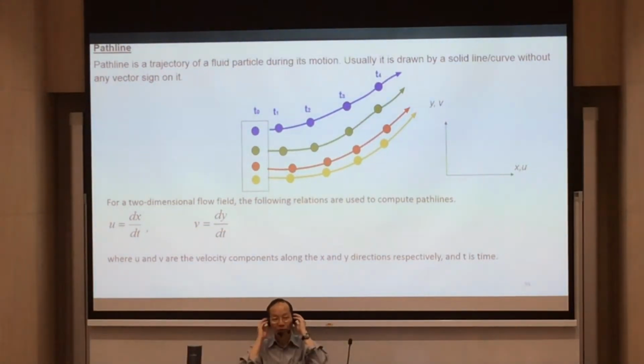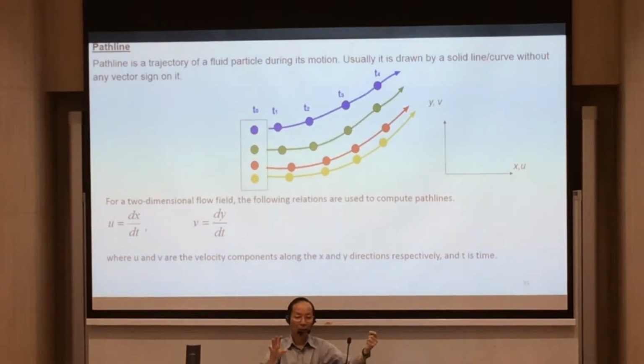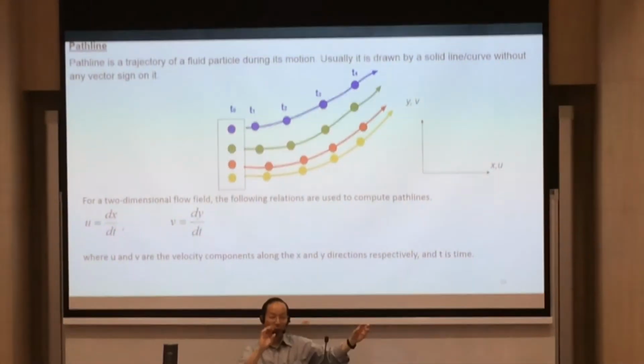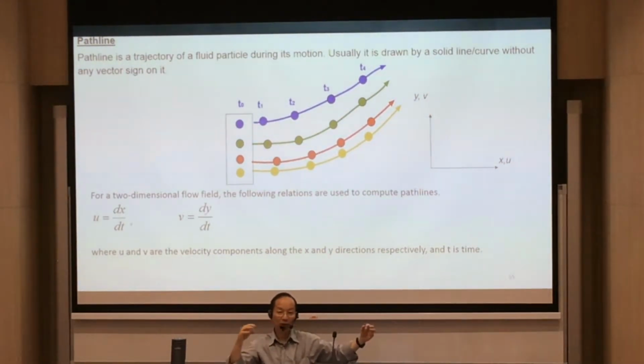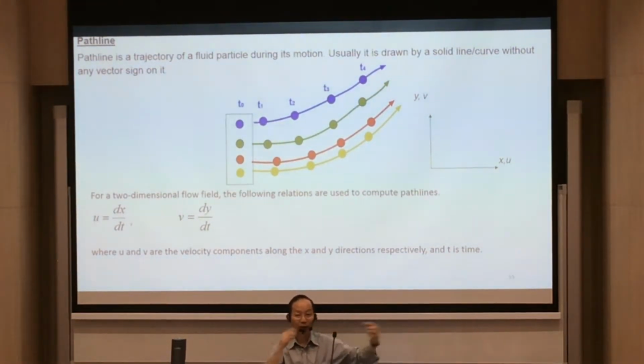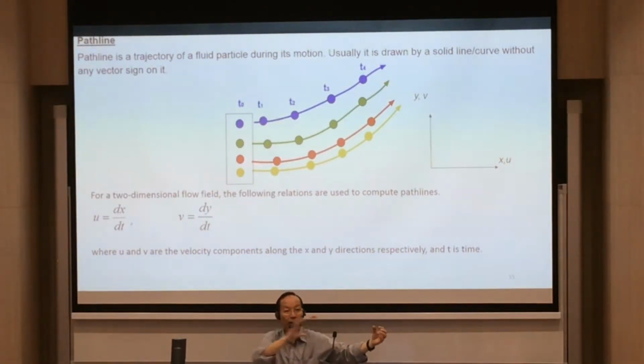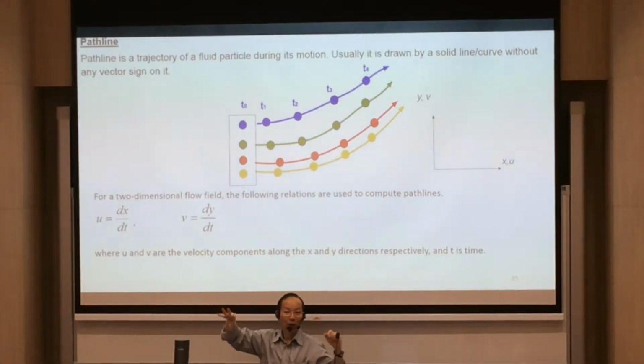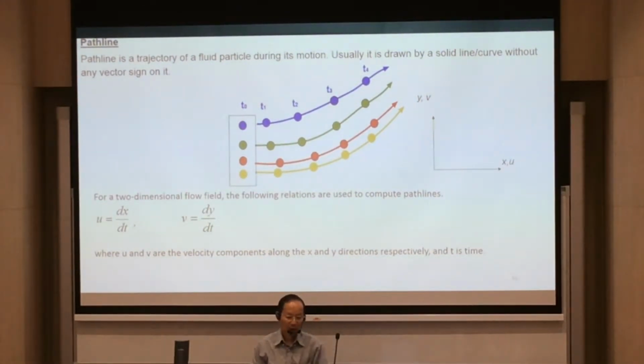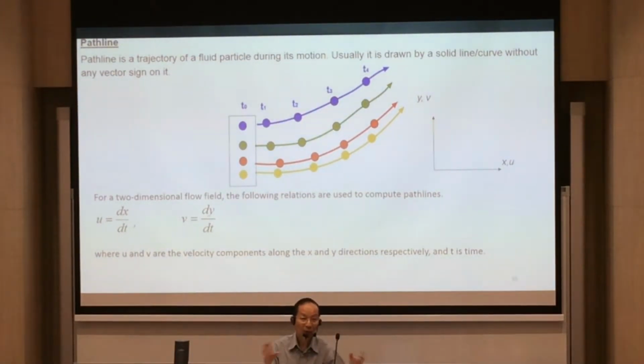Many things which physicists and engineers cannot understand or cannot solve, they go and do flow visualization. For example, you inject a dye in the fluid, like Reynolds did, and you are able to say that at a certain flow rate, the flow becomes transitional, sometimes laminar, sometimes turbulent. You can see the dye follow the flow of the water in the pipe. When you open the valve even more, the flow goes faster and becomes very turbulent. So physicists and engineers use experimental observation to complement their theoretical analysis.